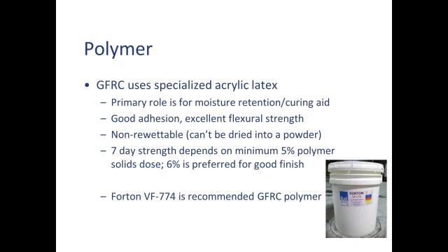The polymer of choice in the industry is Forton. It's been used for probably the last 30 or 40 years worldwide. It has a very, very broad and long track record, very good success rate. It has a lot of specialty additives, defoamers, wetting agents in it that basically have tuned a generic polymer to be a high performance polymer for GFRC to give a very high surface quality.